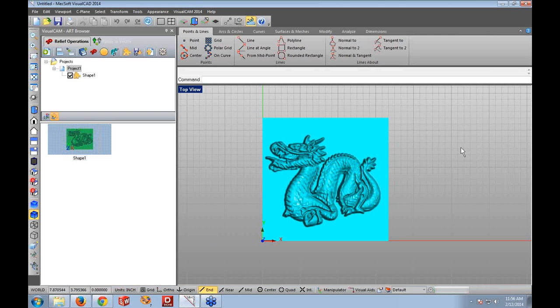All right, and to get back to Ray's question, it was about the placement of parts. Okay, in turning, or is it nesting placement of parts? Must be nesting, Uday. Scott, would you want to answer that? One of the things we didn't show is once you have selected the outside boundaries of each one of the parts as it's staged, in the list that is created, you can click on the name and it will highlight which part it is on the screen. That's how we relate the name in the list to the geometry on the screen. I hope that answers this question.